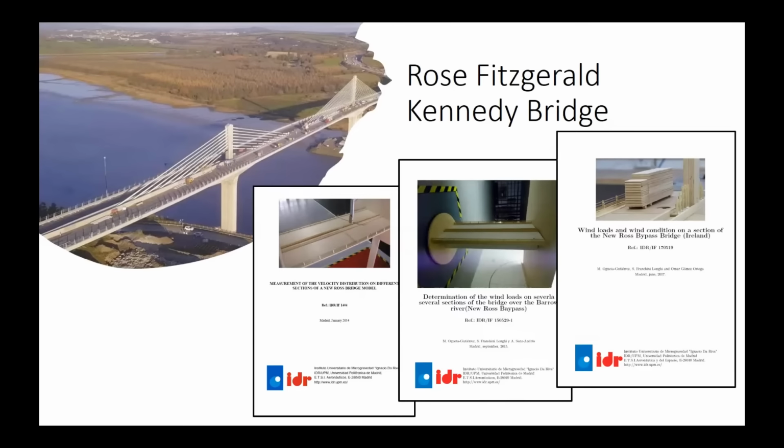So fortunately, I have access to the wind tunnel testing reports that were prepared for this project. And what's particularly interesting, if you see in that picture of the third report, is the model truck vehicle that was used in the wind tunnel. It's made of little bits of matchstick and chipboard glued together. So, you know, that's a further indication of the limitations of wind tunnel testing. The vehicle in these tests is stationary, it's not moving, and its geometry is quite limited.